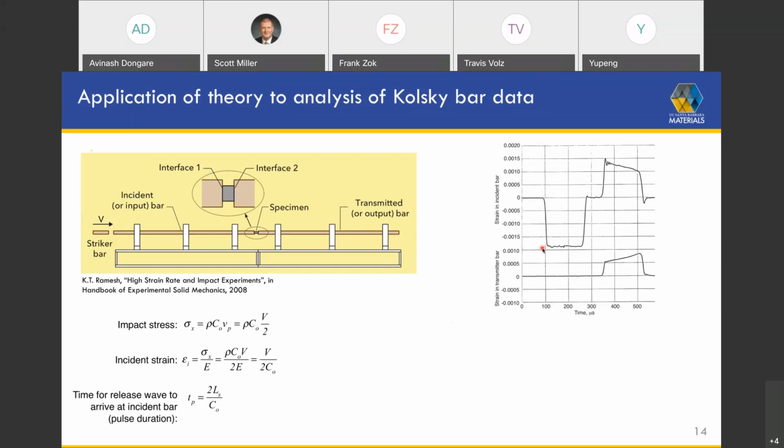You can't say the same thing about a copper alloy or an aluminum alloy. Copper and aluminum in pure form have yield strengths in the low single-digit megapascals, whereas with iron, it's in the range of maybe 100 or 150 MPa.